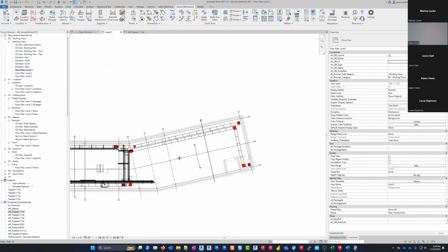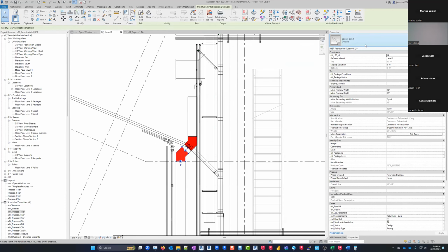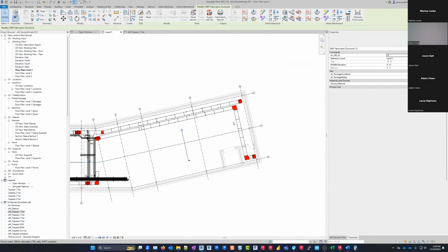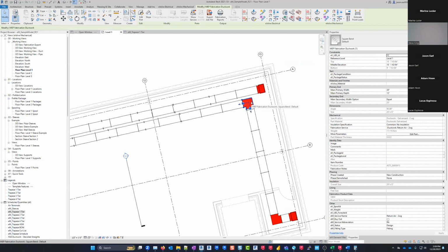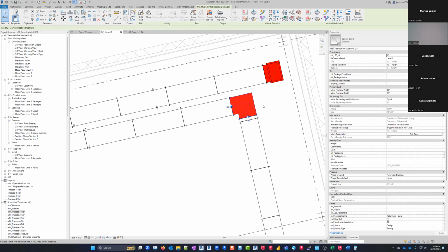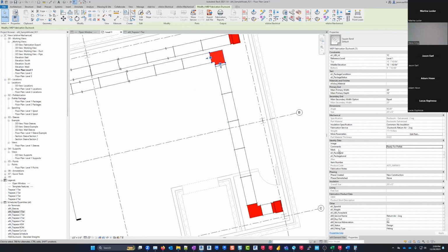So now when we apply that filter, we can see everything is not red anymore. Only the families for square bend are filtered here. Now at this point, we can start to get more advanced if we want. We can get more specific with our filter. So for instance, let's say I've got some in here. Maybe this is ready for prefab, right? Maybe we wouldn't type this in one element at a time, or we might have it in other parameters. But for the example, this will serve us just fine. And maybe this one is needs review. All right. So I've entered some additional information in here.